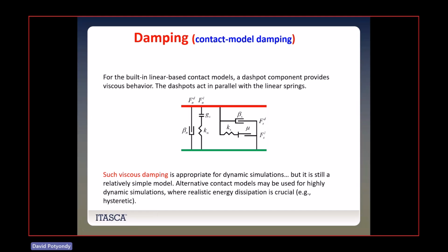This local damping is not physical. It's a magical thing to very quickly stop the vibration of the system, because every single guy gets a specially tailored force to make that guy stop shaking. But for example, if you take a box of grains of sand, you model them as particles, you let them settle under gravity into a box, and now you slowly start squeezing it, you are exciting the system, and that whole system is going to start shaking like those tennis balls and springs.